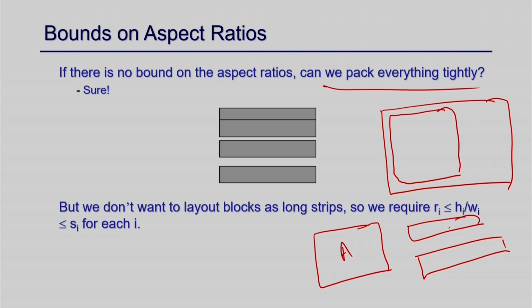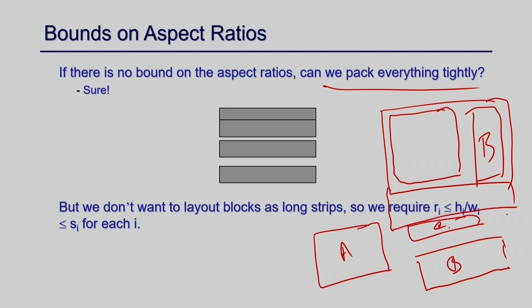If you place one of them here, say this block is something like this, their length is more than this, so they cannot be placed this way. So, suppose this is B, and I want to place it this way. Now what happened? There is no way to place C, because it is all fixed and there is no place. Then basically you have to increase the area of your design, the chip area, just to place this C here, and a lot of space remains vacant.